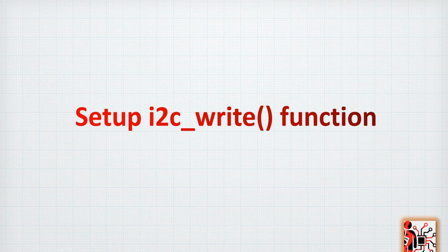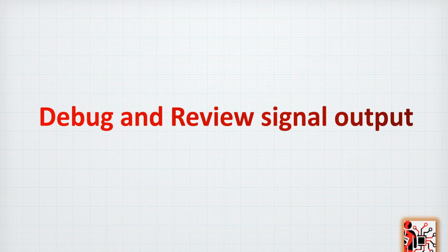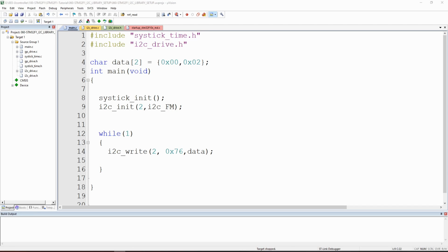So we just finished writing a modular write function. We can jump and see the signal and do some debugging, if any. Okay, we are reaching the most exciting time, when we try to see if the code is working or not, and we try to debug if something happens. So let me first start by correcting this. As I was expecting, it was 78, not 76 hexadecimal.